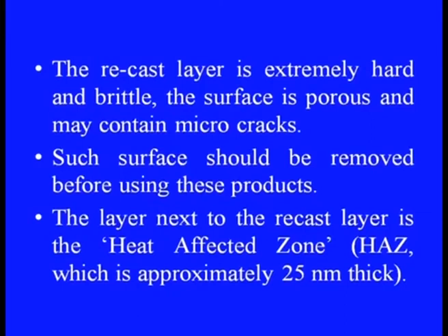This thin layer, say about 2.5 to 50 micron or so, is known as the recast layer, and subsequently we may have to use some other secondary processing technique to remove this recast layer if the nature of the job or the application demands so. The recast layer is extremely hard and brittle. The surface is porous and may contain micro cracks, which is not a good characteristic of a machined surface. Such a surface should be removed before using these products.